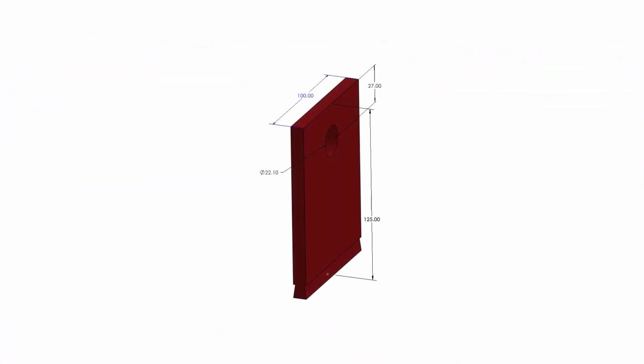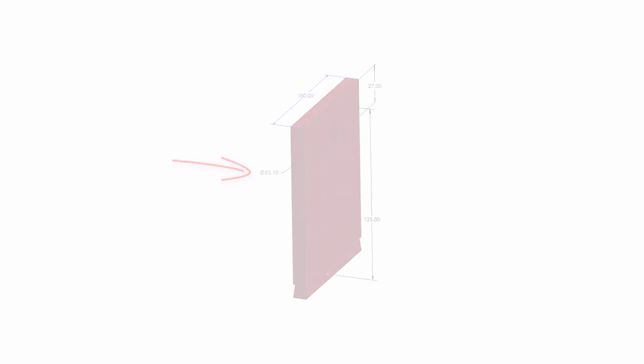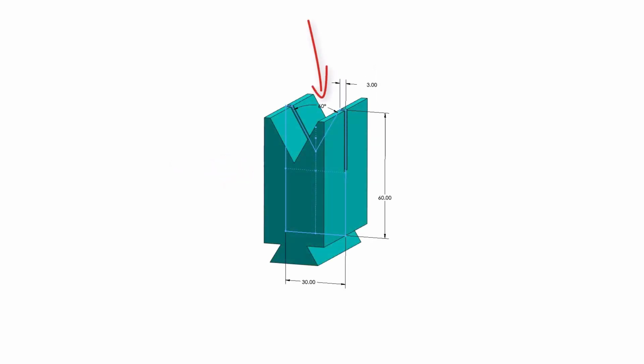The walls will be about 125 millimeters tall, with a hole about 0.1 millimeters bigger than the bearing. Again, every 3D printer will print differently, so experiment with sizes. The dowel holder has a 60-degree opening to cradle the dowel to be cut, and has a slit to accommodate the saw blade.